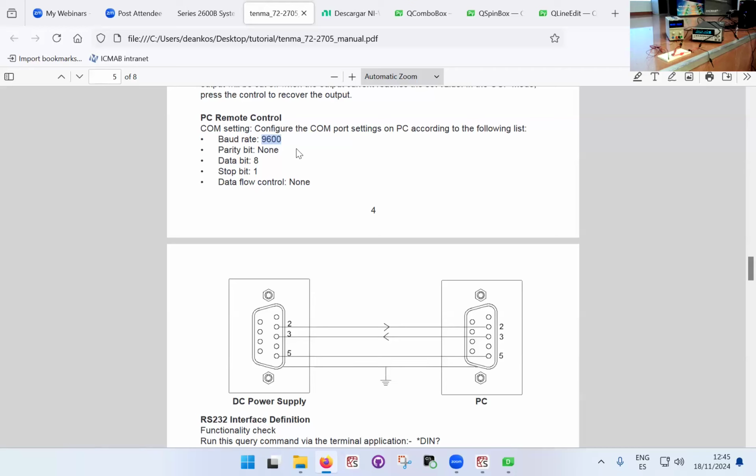For example, if you're communicating with an Arduino, which has a serial port, you can set the baud rate to be 9,600, 115,200. There's a whole range of different values that you can choose. Generally, you shouldn't be choosing arbitrary numbers. There's a set of values that you can pick and use. But in this particular case, all the manual is telling me is to use 9,600. Maybe it's compatible with other values, maybe not. So I'm just going to stick with 9,600.